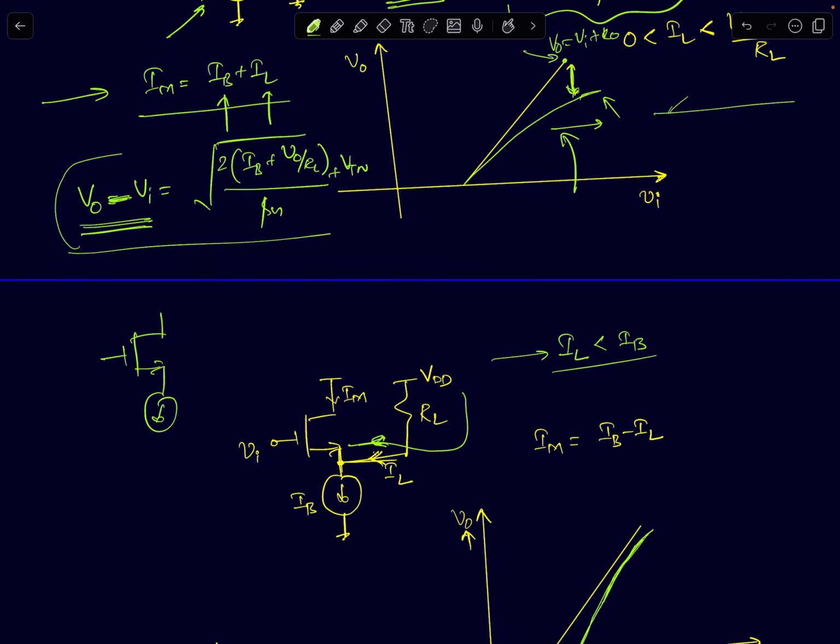If I just capacitively couple my load, then you will have a signal which is going to go both positive and negative. So whenever it's positive, you will draw current, push current into the load. Whenever the voltage across the resistor is negative, you will pull current from the resistor. So these things will happen. Okay, so you can have currents flowing in either direction.